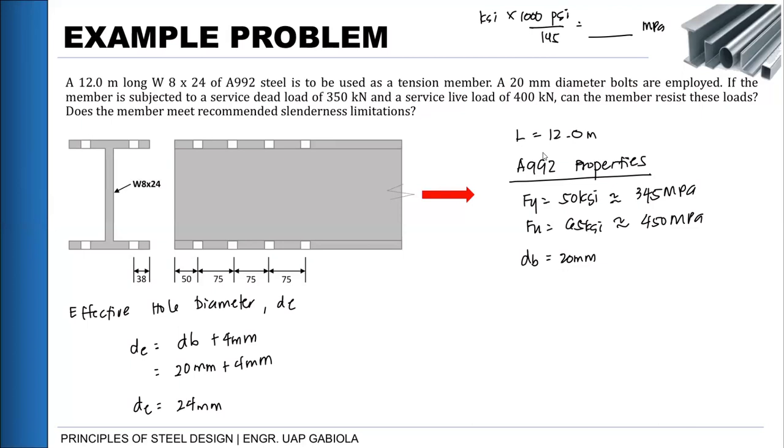All right. Next, we have the given loading. So it is stated here, these are service dead load and service live load. Take note, once service loads ang pinag-uusapan natin, it means that the loads are still unfactored. Meaning wala siyang magnifier, wala siyang load factor. So if our design philosophy that we will employ is LRFD, we need to use our load combination to arrive with the most critical value of our force.